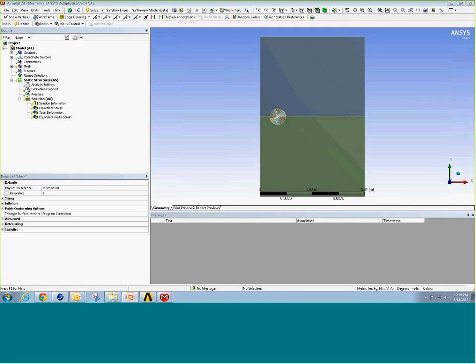So I'm going to switch now, and I'm going to show two different demos. The first one is going to be a pre-meshed crack. That means you've built your geometry such that the geometry contains a crack in it. You can do this in 2D or 3D. If you've already created geometry, or if you already have a mesh, you can bring it in through FE Modeler and then just identify where that crack is. That's what I'm going to do, and just to make this fairly easy, I'm going to do a 2D model, just for time's sake.